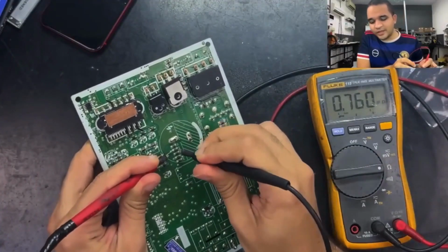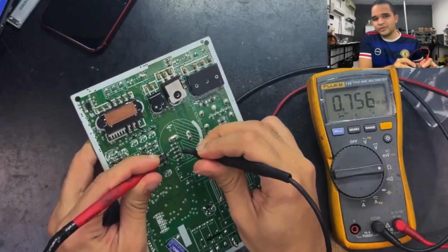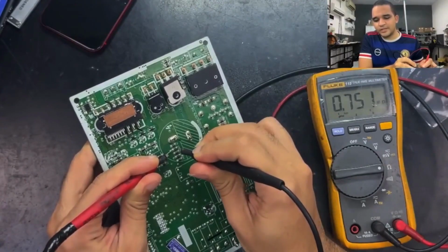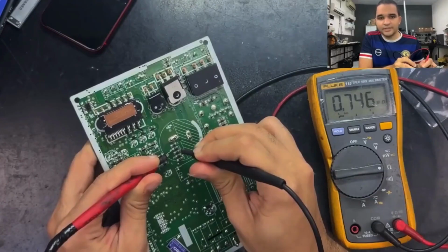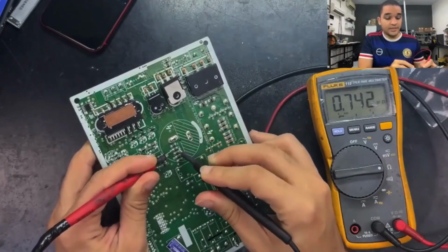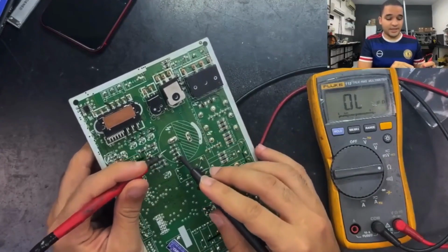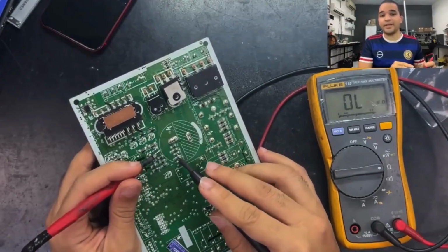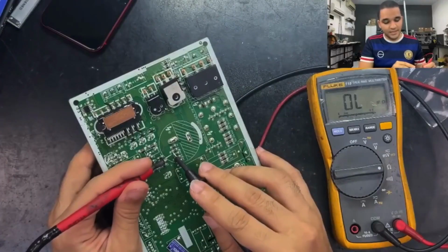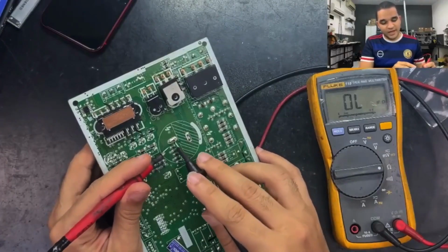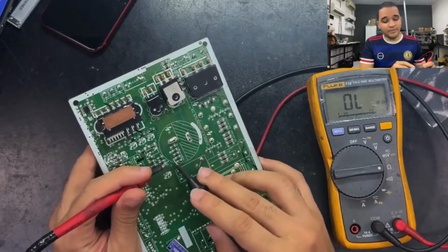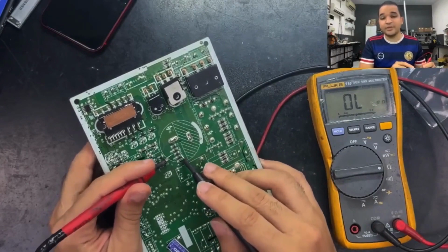It was stated to be 700, which is equivalent to 0.7 megohms. However, it was actually 751 kiloohms. Right? It's wrong, right? Yes, but I'm measuring it in the circuit. To measure it right, I need to open it. So I take one out of the line. When I take one out of the line, I disrupt the series. Then the value of all of them will give their correct real value.